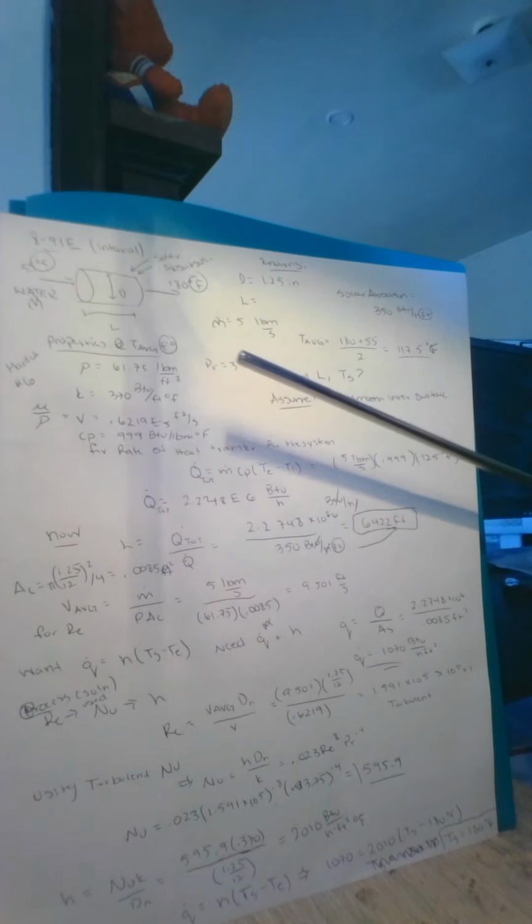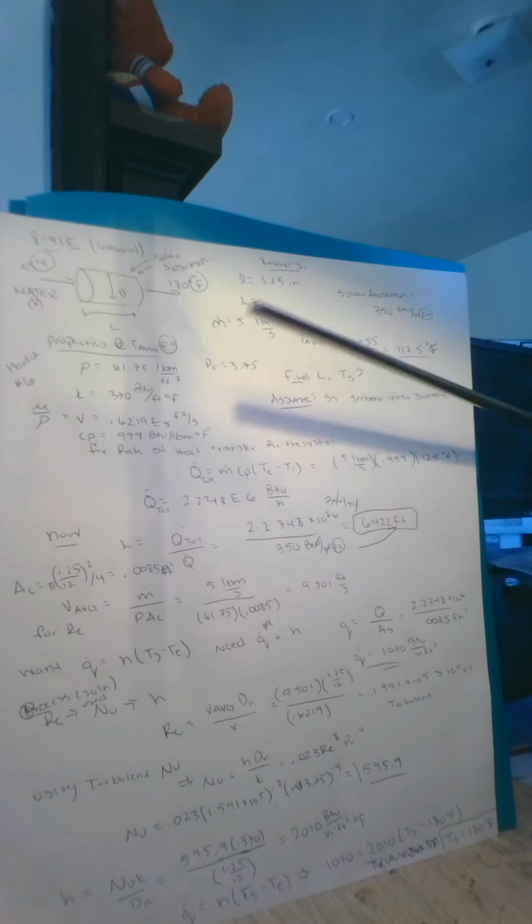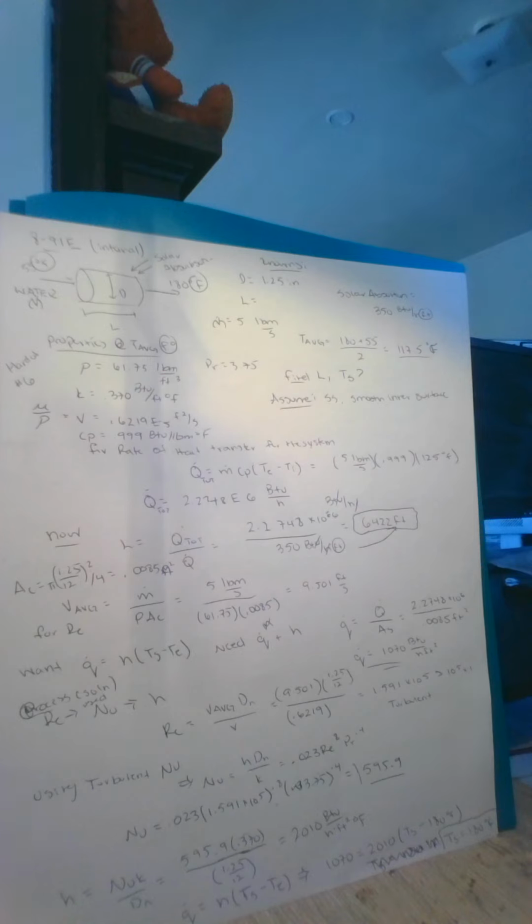For this question, we had an internal flow type problem with water traveling through a pipe with an inlet and outlet temperature, and then there was also some absorption from the sun. Given that, we then found the T average again and the properties for that T average, and then we also needed to find the total heat transfer for the system. So we used m dot Cp times the change in temperatures. Once we had that, we can then use that in relation with our given heat to find the wanted length for the section of the pipe.